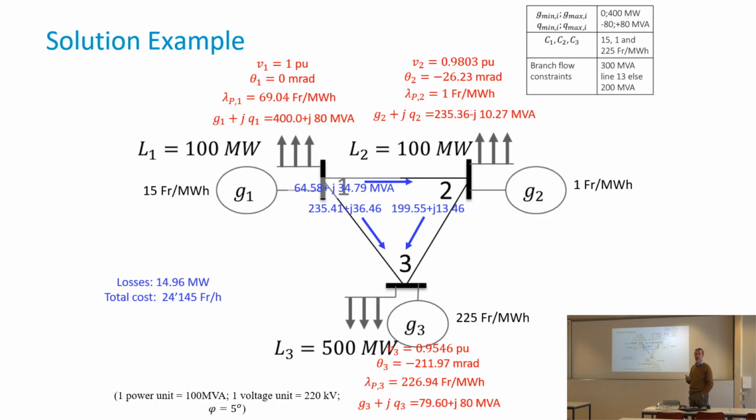It's an average 0, except that, and that would be true if we had grids with 0 resistance on the lines. But because there is a non-zero resistance, if you transfer oscillating power, then there is always a power loss due to that. So the reactive power causes losses. And since it serves nothing, nobody will pay for it. The consumers here will pay for 100 megawatts of each, but the reactive power, nobody will pay for it because on average it's 0, nobody receives it. But on the lines, it will dissipate heat.